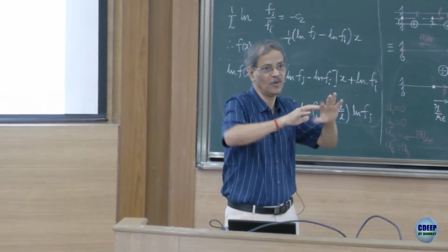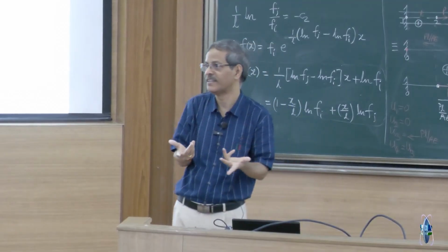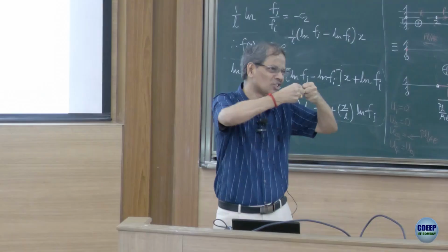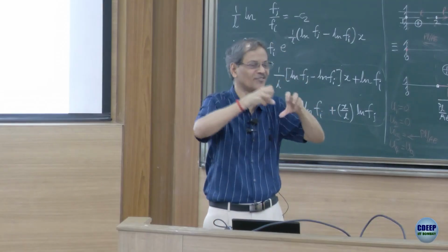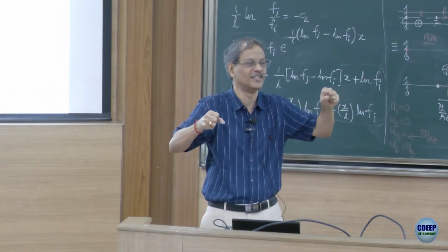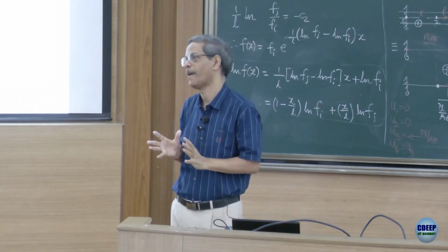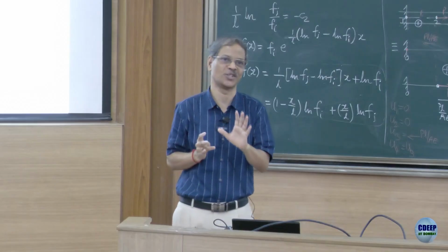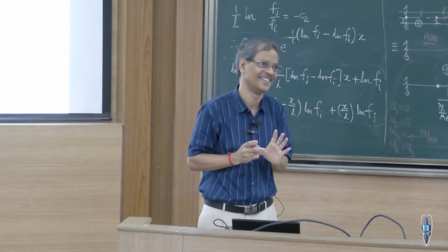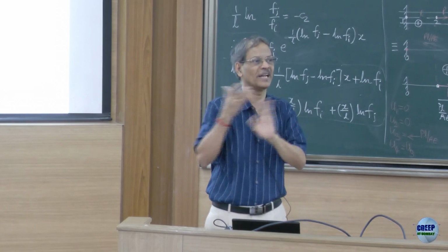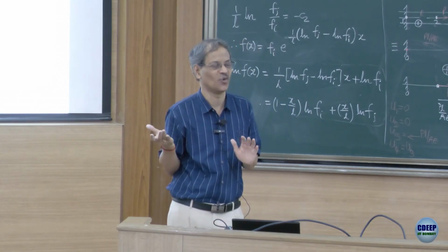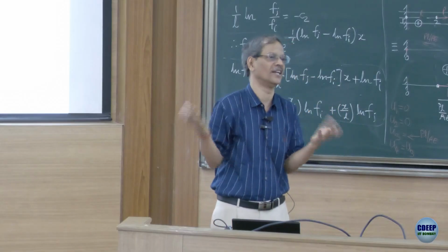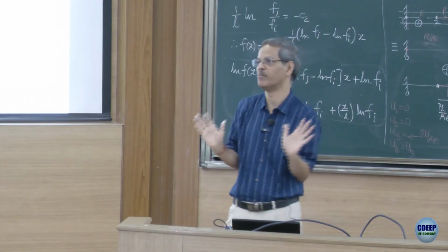So, you could flip this argument and say that this 2 by 2 perfect square element, I am actually distorting it, stretching, rotating, whatever you want, into this quadrilateral. But as long as I use linear distortions, transformations, a straight edge can only become another straight edge. So, 1, 2, 3, 4 perfect square will be 1, 2, 3, 4 quadrilateral, that is all that it can be.